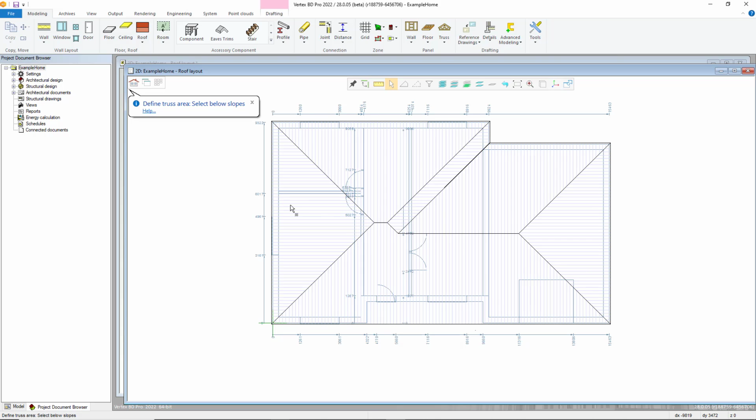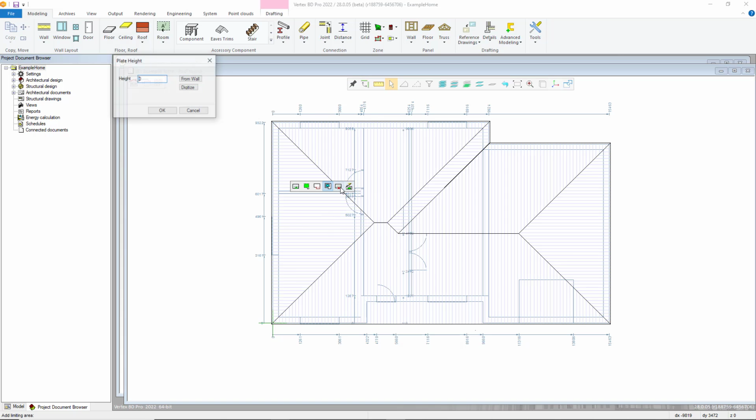If I have any seam plates or roofs under the above slope, I can select these. However, if like in this example I don't and only have walls and roofs, I can utilize the define limiting plane function from the right-click contextual toolbar to add in an invisible plane. This function allows me to specify the height of the plane.